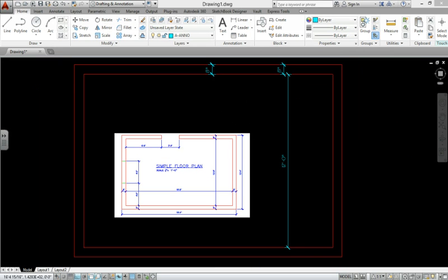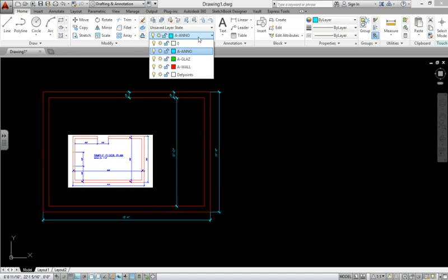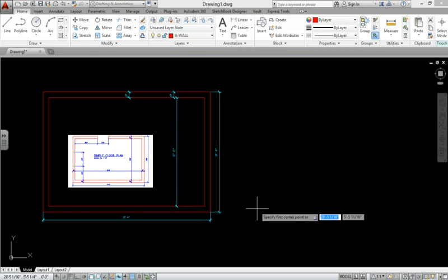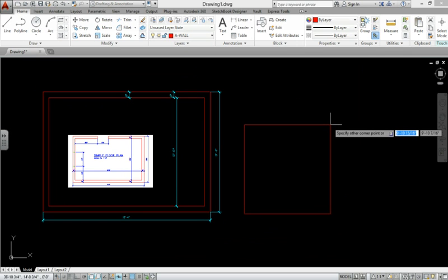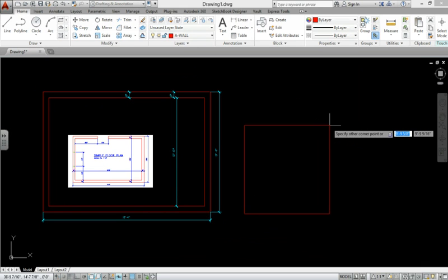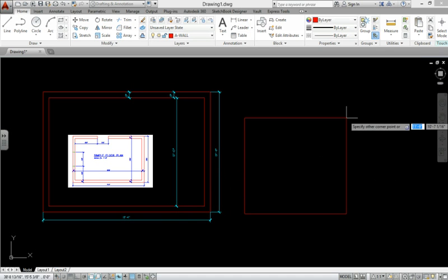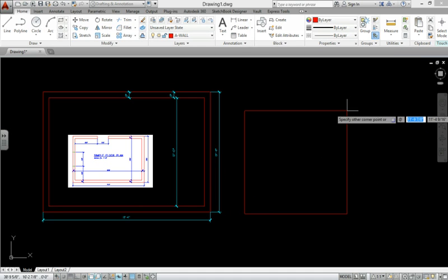Using the rectangle command with the same numbers. There's going to be something new you're going to learn here called relative coordinates. Pick rectangle. Pick any point you want to start in and point to the upper right. You're going to type in the relative coordinates of the next 2 points, which happens to be the horizontal and the vertical distance, which is x, comma, y, like you would think in the coordinate system. So you type in the @ symbol to activate it. So shift 2 basically.